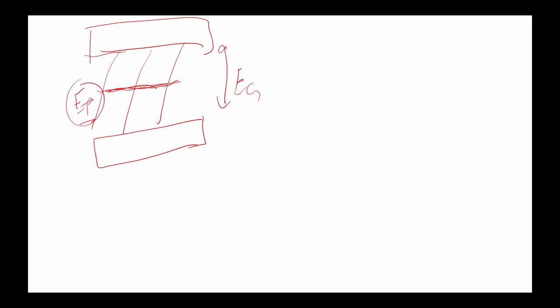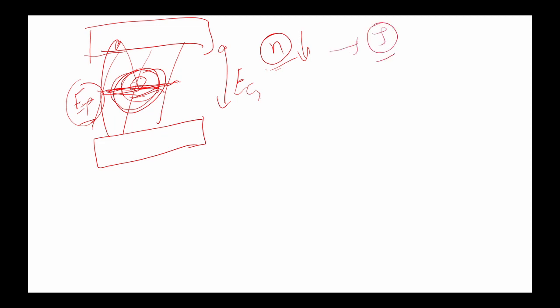So when we excite an electron, that electron can come here and get trapped. We were supposed to get n number of electrons, but because of the trapping of electrons, we are getting less than n electrons. So it will decrease the charge, it will decrease the current in the semiconductor. That will affect our device, so we do not want these traps.